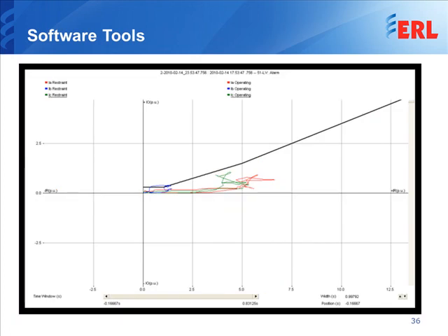When analyzing differential faults, this is a differential view. In this case you have the IO min, the first slope and the second slope, and anything below that black line is the non-operate region, and anything above that is the operate region. So if anything went above that region, it means that the relay operated. In this case it looks like the relay operated, and it looks like it was an external fault. So a review of the IO min settings might be necessary here, because certain faults are higher than others, and sometimes through faults can be really high and the settings might be too sensitive.